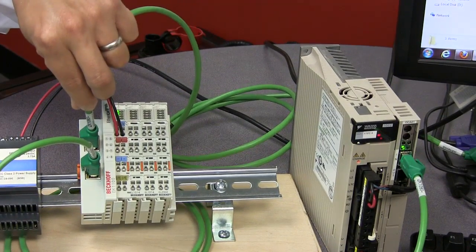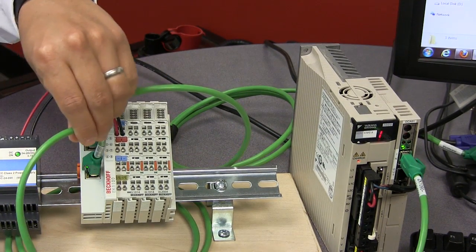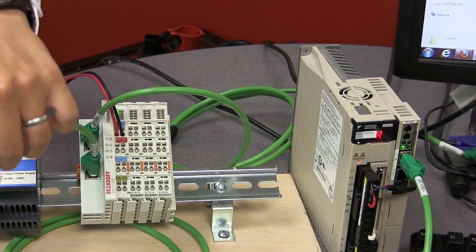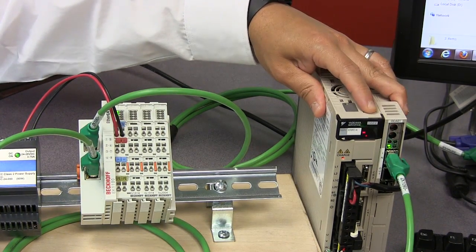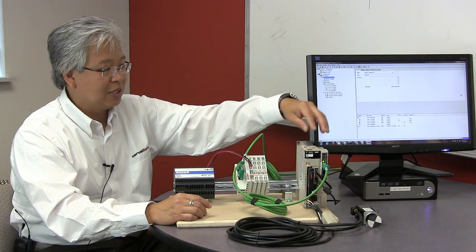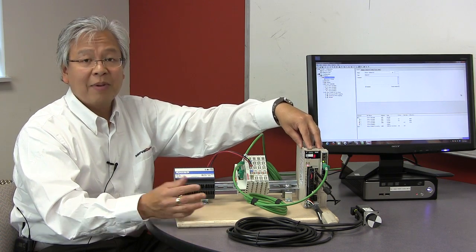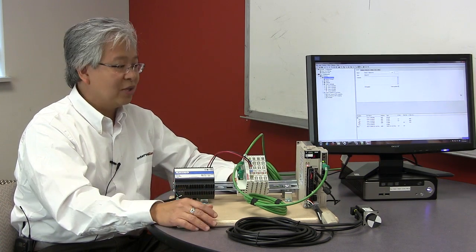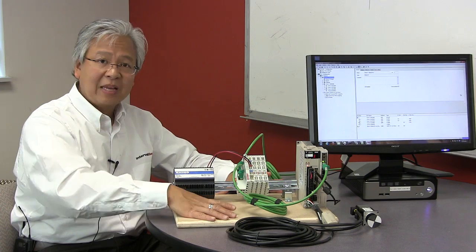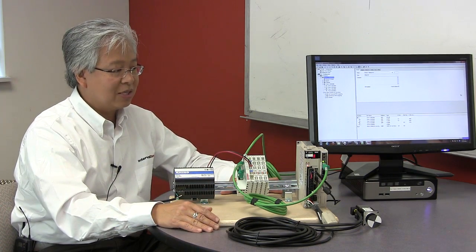Then if you look here, there's an output cable as well. All EtherCAT modules always have an input and output. Here's the output, and you can see this single Cat5 cable is now going to this Yaskawa drive right here. This is a single drive. Your application could maybe have tens, hundreds, maybe even thousands of drives. So again, hopefully you can extrapolate this into your own example.